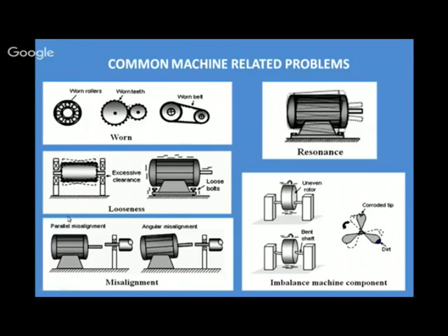Another type of problem is looseness, that is at the time of installation, if some bolts are being kept loose, those will produce some vibrations or motion in the moving parts. This motion will propagate over time and will become severe. So therefore we have to have different types of sensors being placed here to monitor all these types of faults.